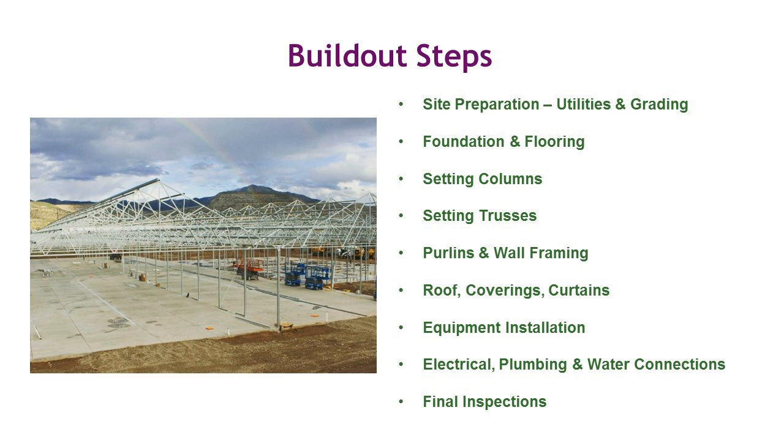Let me interject here real quick. I want to point out, and this picture is a great spot to do it, when you look at these trusses, these are our trusses. They come pre-assembled. Our trusses are welded one-piece construction. So they're stronger because they're welded together, but also you don't have to bolt together all the tiny pieces of each individual truss. They come pre-assembled, ready to be set. This decreases your build time significantly compared to assembling all your trusses on site, saving you quite a bit in labor, ultimately.